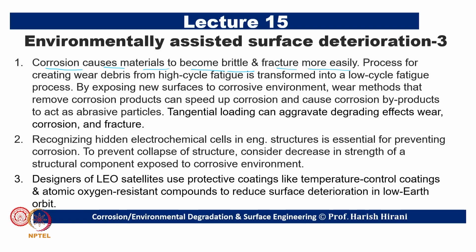Now, this is what I mentioned earlier, the process of creating wear debris from high cycle fatigue. In normal conditions, when there is no corrosion and the environment is very good, every wear debris particle will separate after maybe 1 million cycles, 10 million cycles.